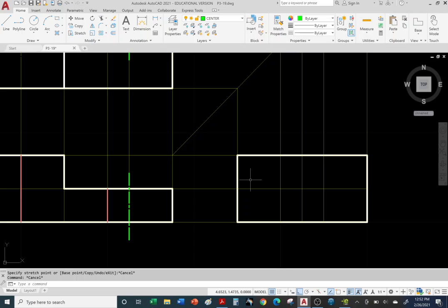All right, so let's complete the right side view. Let's go to visible white object layer. Okay, use the line command. And again, from every corner, let me turn on object snap. You can track across. So there it is. There's that corner. And click. And click. There it is. Okay, right click enter to exit.